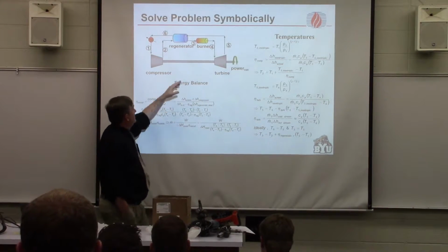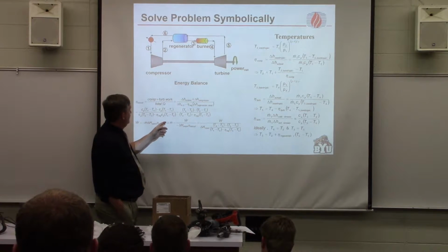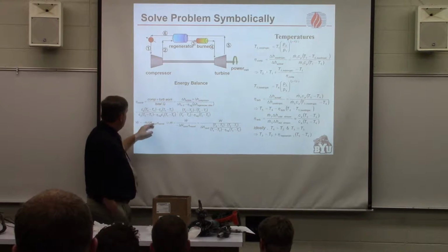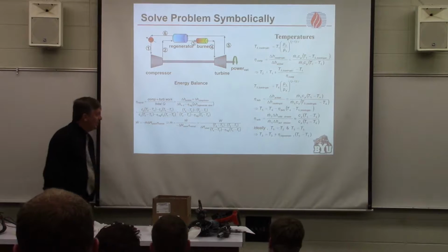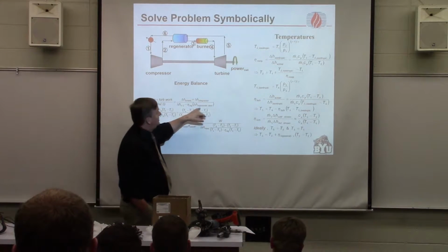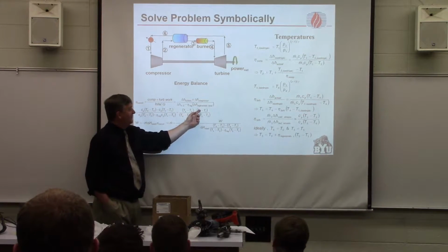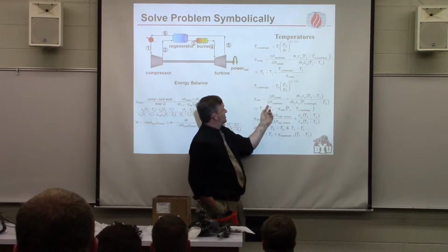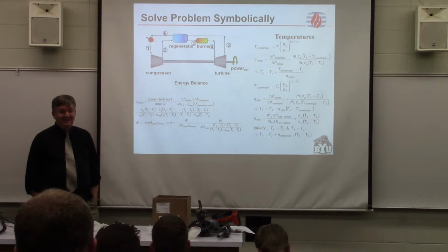This is the amount that you put through the burner and the regenerator minus the amount from the regenerator, so the overall efficiency just ends up being this function of temperatures. To get T2 and T5, you have to know the efficiencies, so T2 and T5 are given by these expressions here. Does that all make some sense to you?